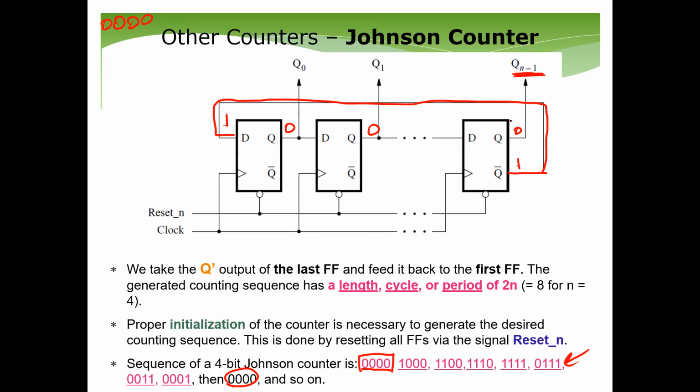For this implementation, it will start at all zeros. Next state is going to be 0001. Okay, so this will stay at 1. This will change to 1. Next cycle, that's going to be 0011. After that, it's going to keep progressing up until it reaches all ones. When it reaches all ones, see what happens.